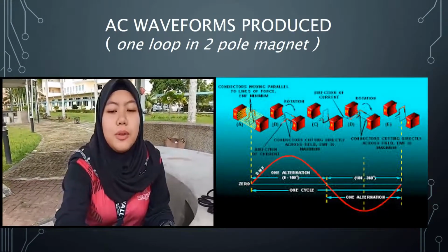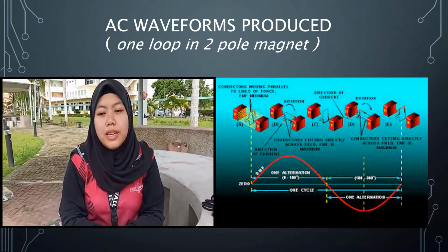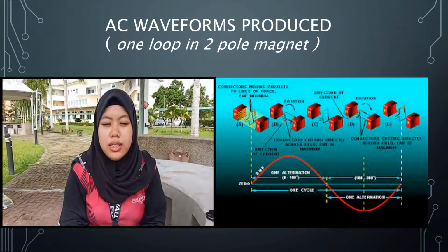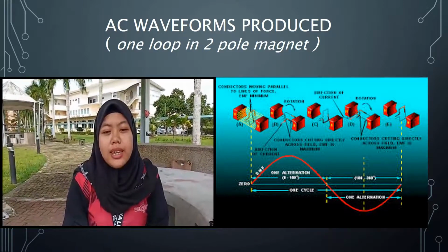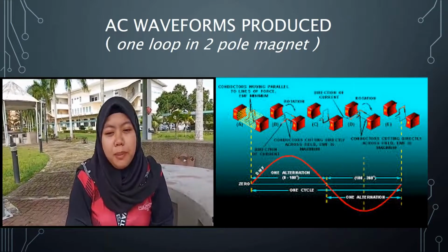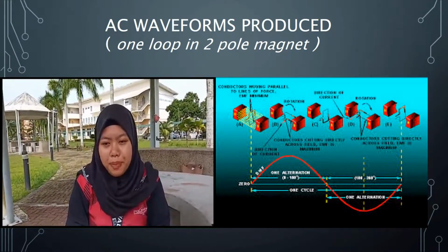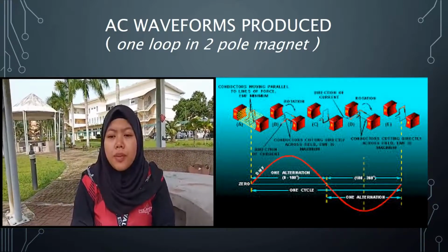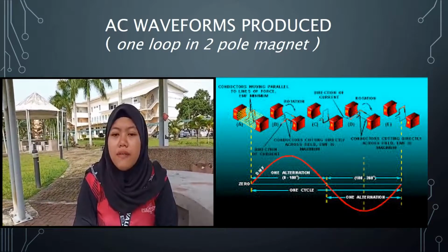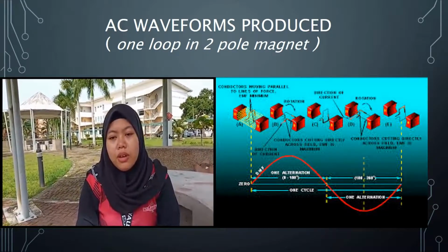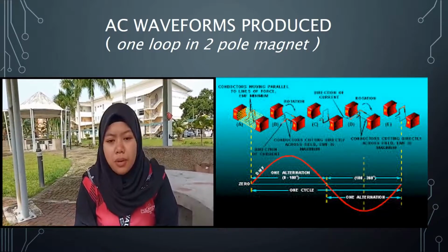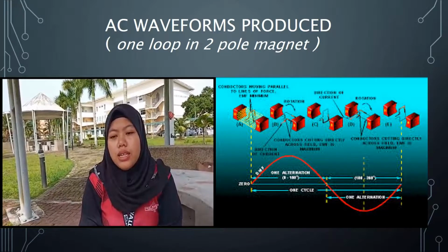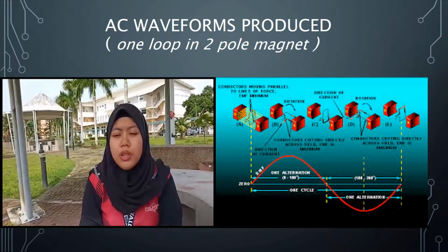The figure shows a suspended loop of wire conductor being rotated in a clockwise direction through a magnetic field between the poles of a permanent magnet. For ease of explanation, the loop has been divided into a dark half and a light half. Notice in A of the figure that the dark half is moving parallel to the lines of force. Consequently, there is no cutting of lines of force. The same is true of the light half, which is moving in the opposite direction. Since the conductors are cutting no lines of force, no EMF is induced.